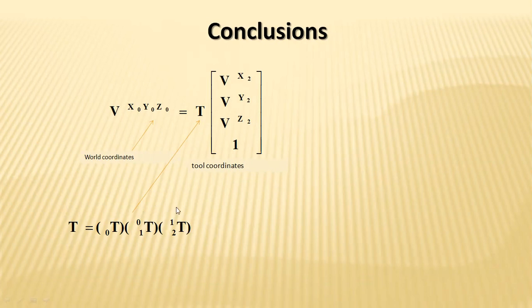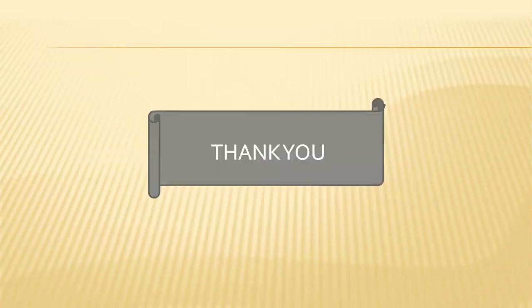And based upon this, in this way, we will be substituting the values. And from the examination point of view also, the theta values will be specified to you, A values will be specified to you, D values will be specified to you, and phi value also will be specified to you. And that is the way of calculating the position of the end effector upon the overall transformations by utilizing the DH parameters. This is the derivation related to the DH parameters.